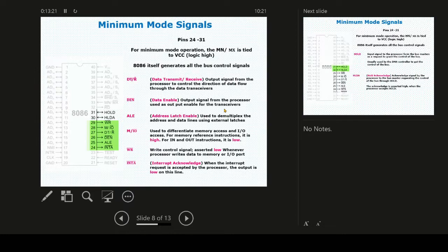So now comes the interrupt acknowledge. What is interrupt acknowledge? Previously Shashwata mentioned the interrupt command. What is the interrupt command? If a new external device wants to connect with the microprocessor, then this interrupt command comes into action and sends a logic 1 to the CPU, saying yes, I can receive or transmit the data. It gives the request, and the CPU responds through the interrupt acknowledge pin, whether it should accept the data or not.